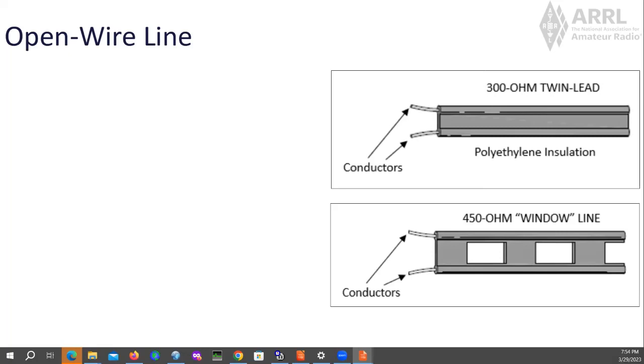And you can actually make this yourself if you use two wires, and there's a formula you can use to use the proper spacers to space them apart. I think you can buy one made like that, so it's 600 ohms, but according to the size of the wire that you use, there's a spacing that will make the impedance that you wish to have your line.